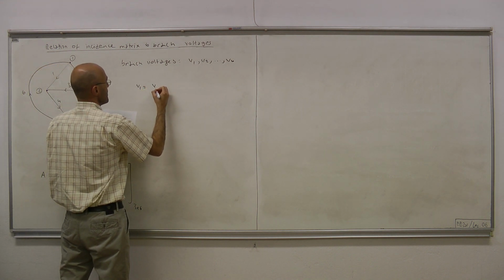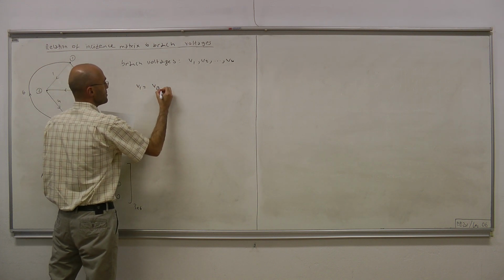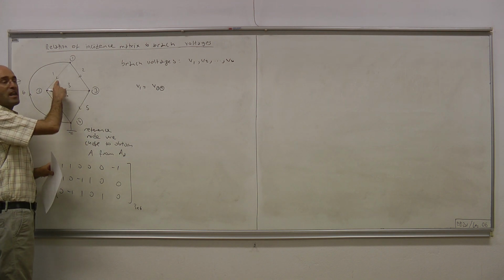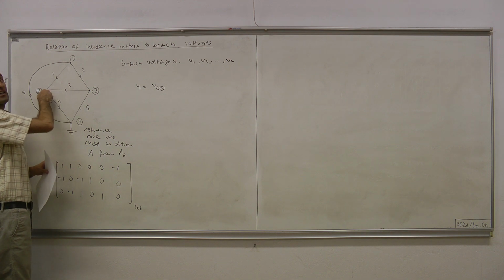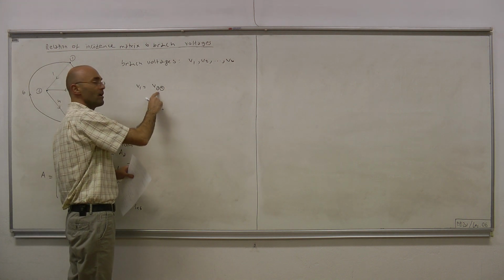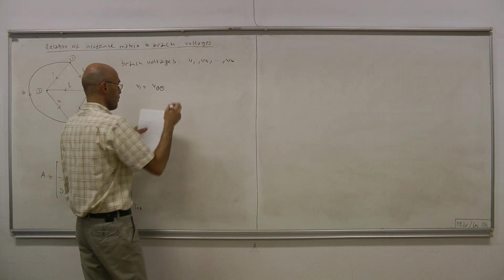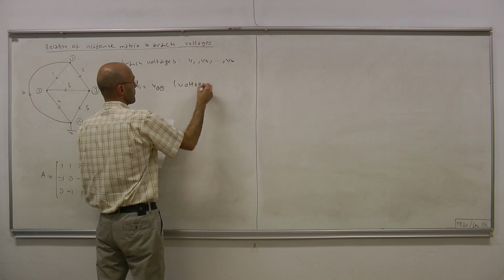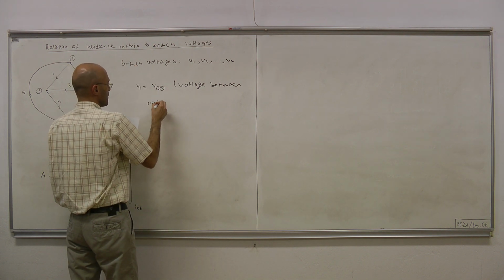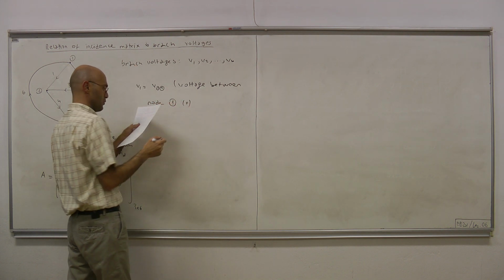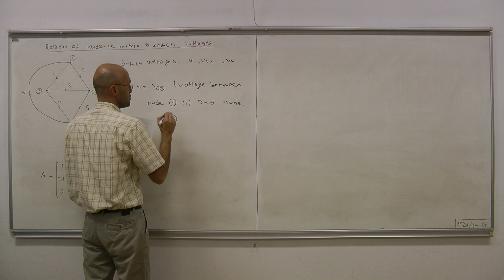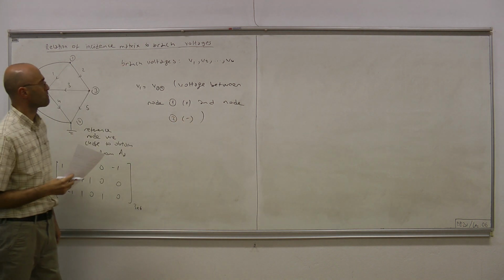In other words, by V1 we mean the voltage between the first and second nodes, because branch number 1 appears between the first node and second node, and the direction is from the first node to the second node. Therefore, here we have 1 and 2 here: the voltage between node 1, which is our positive labeled terminal, and node 2, which is the negative labeled one.